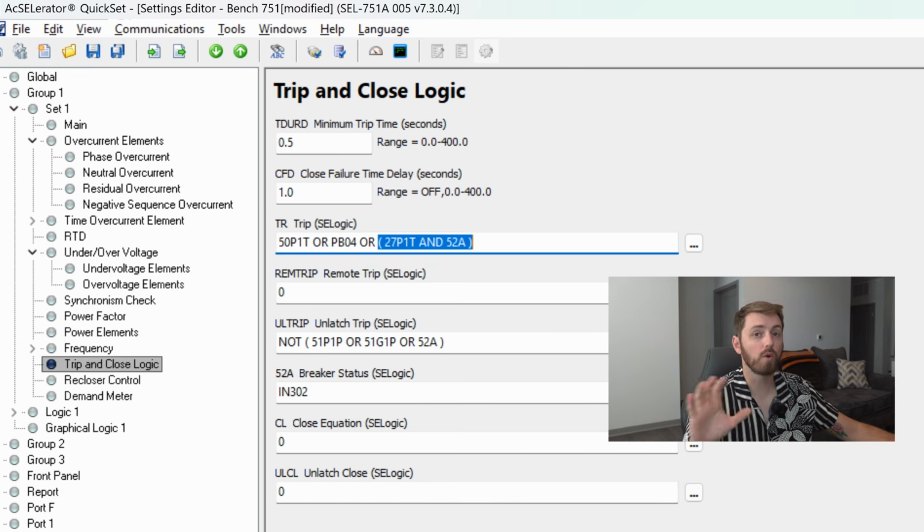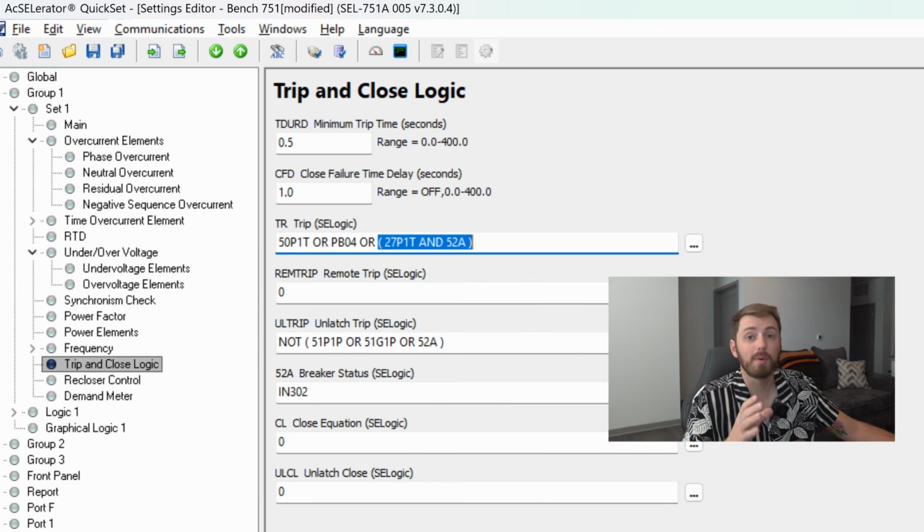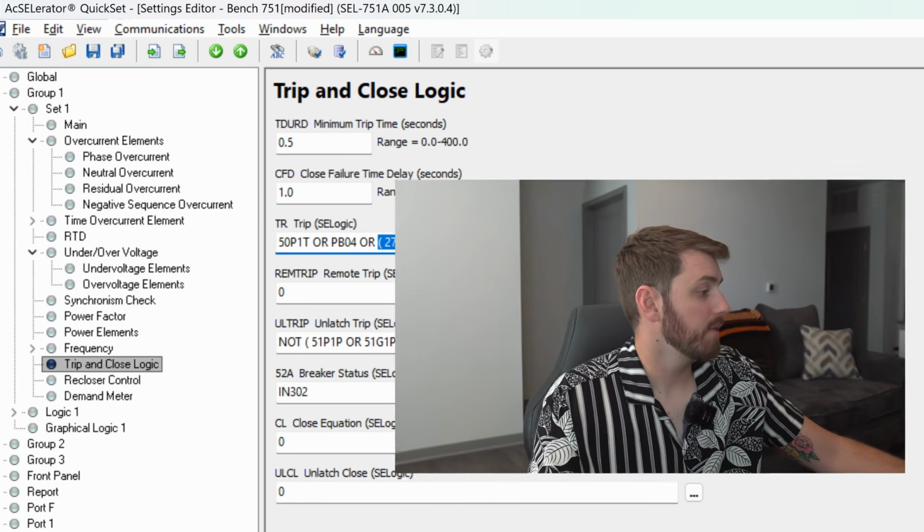We don't generally want to hold the trip circuit closed or hold the trip circuit energized if there's an undervoltage, like just a bus outage, some normal thing, we just have it off, whatever. I don't need to hold the trip coil for the breaker energized. So you might see this a lot. So that's what we see here. We use programming logic to make the relay physically operate the system the way that we want.